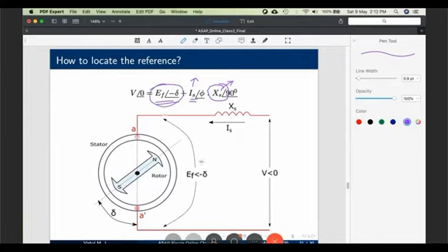Can we put a voltmeter here? See, this is the EF at angle delta. Can I put a voltmeter here and find out, or a CRO here and find out? Actually, that is also not possible. Why? Because this terminal is a fictitious terminal. This terminal does not exist in real life. This is the only terminal which is accessible to man. Here we apply voltage V. This EF sits behind the stator synchronous reactance. So this terminal is not accessible at all to a human being. We can only access this point, where we apply V. So measuring or calculating EF is not possible.